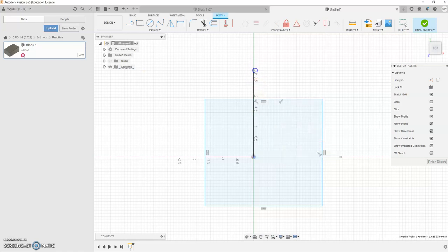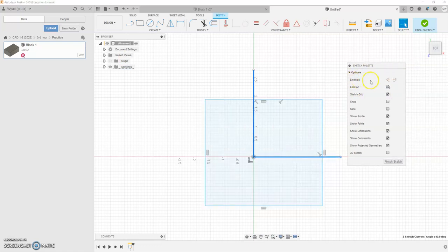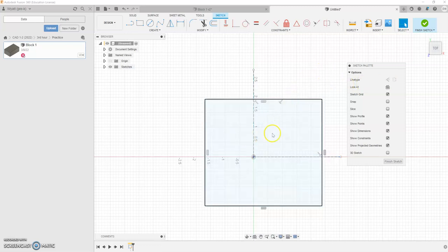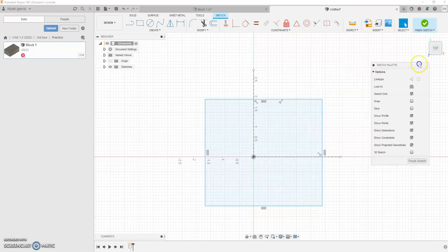Yes, we can still change the length of them, but they're still fully constrained. Now hold my shift key down and select both of those lines. Holding shift, click there, and over in this box, remember you're going to change those to construction lines. Right underneath the line type, it says construction when you hover over it. Click. Now those are construction lines, which are not selected when you move out there on the screen.